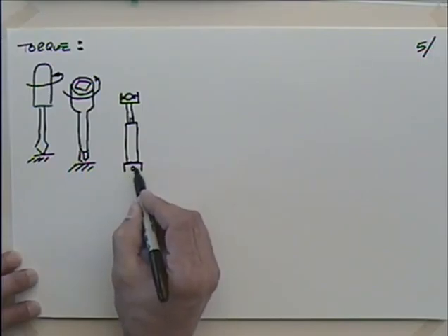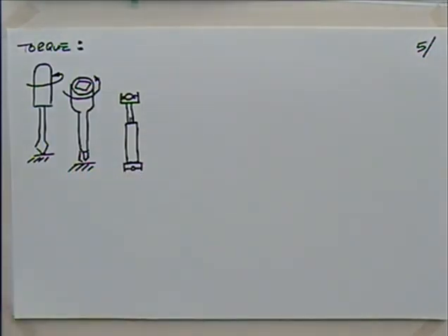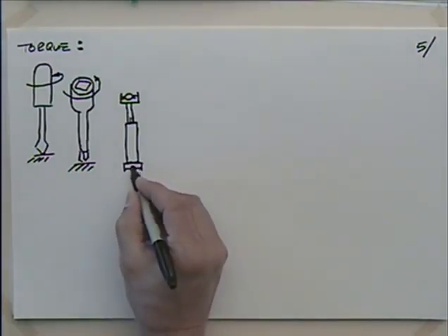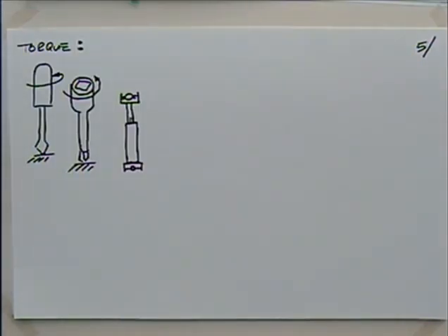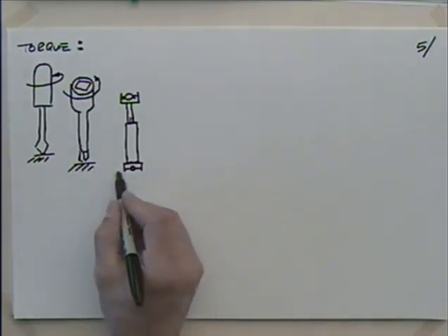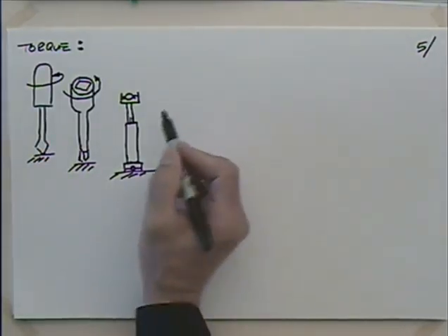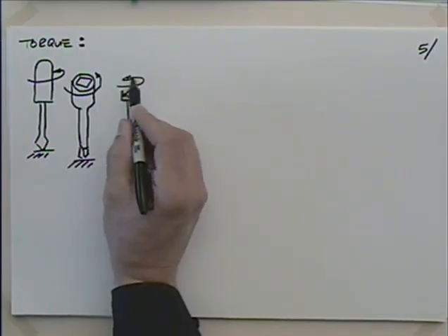No? Yeah? Okay. If you look at your automobile, if it's rear-wheel drive, as the rear axle goes up and down, articulates, the distance from the back of the transmission to that rear axle changes a little bit. So you've got to have something that'll take up that geometry. So you'd have a drive shaft. If you have a front-wheel drive car, you have that same argument, but now at each tire, right? So you're going to have to have something that deals with that. If we were to fix this and apply some torque here, we have that.